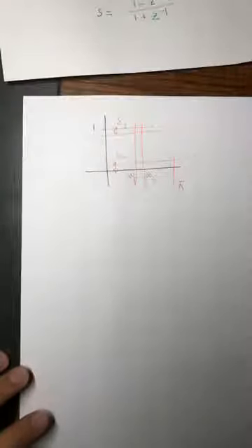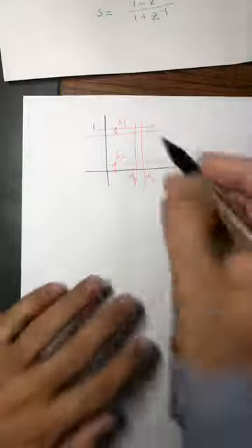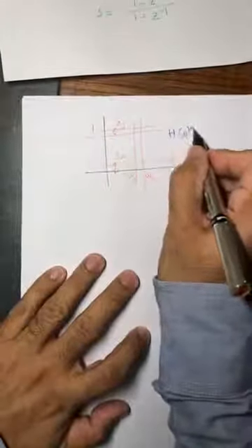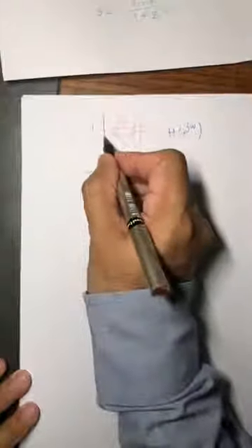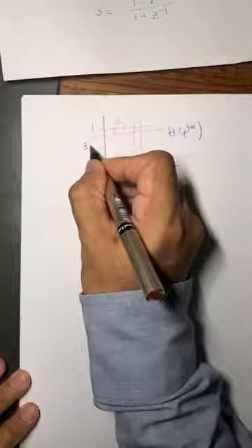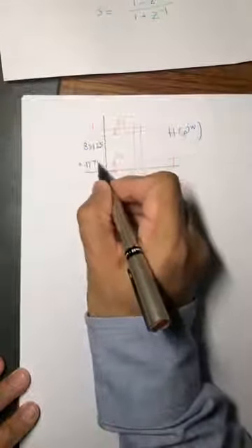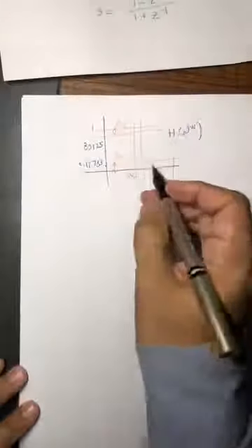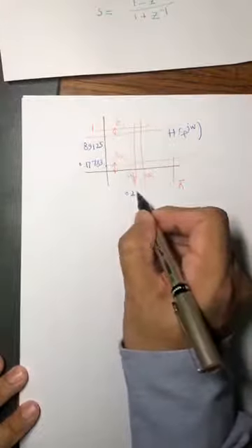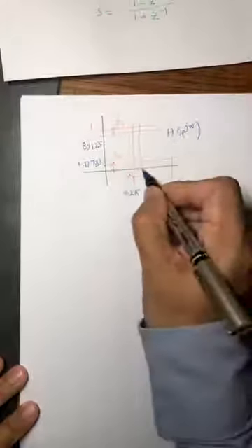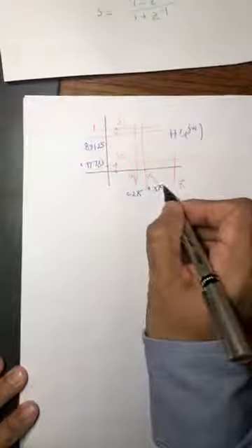So this is what we expect you to provide, these specifications, if you want us to design a filter, and this is the analog filter, H of e to the j omega. These are the specs. So the question which we solved earlier, from the book: this value was 0.89125, and this value was 0.17783. Omega p was 0.2 pi, and omega stop was 0.3 pi, right?